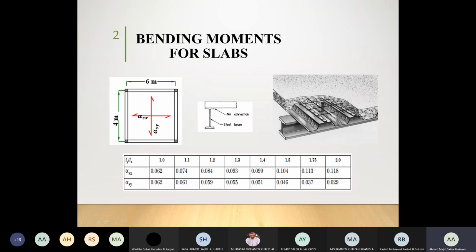And you can see here, can you see that there is a bolt connecting the slab to the beam? Are you able to see it? Yes. Okay, so now with the availability of the bolt, do you think that they will be connected to each other? The slab and the beam? If the bolt is there, will they still act? Yes. They will be connected, right? So if they are connected, we should be considering it to be restrained.